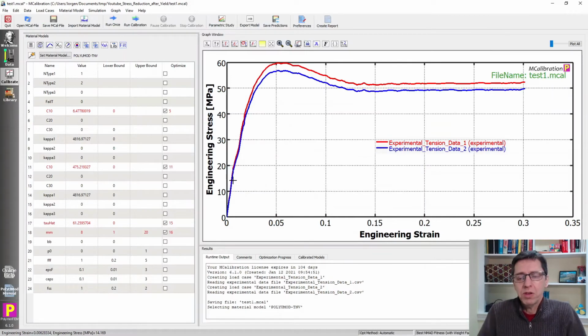It turns out that for robustness and easiness, it's usually better to manipulate the viscoplastic element, the dashpot, in this model. So that's what I will demonstrate in this case. We will also later on talk about how you modify the modulus aspect of it. So here are the parameters. The first network goes from parameter 5 to 10. These are the hyperelastic parameters, and they look fine. The second network has a spring and a dashpot next to it. These are the parameters there, and they look good. The dashpot we want to play around with a little bit here.